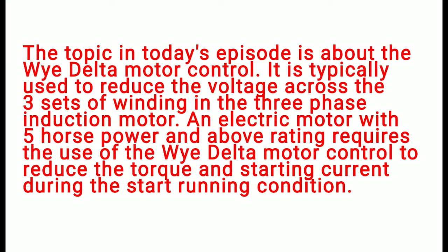The topic in today's episode is about the Wye-Delta Motor Control. It is typically used to reduce the voltage across the three sets of winding in the three-phase induction motor. An electric motor with 5 horsepower and above rating requires the use of the Wye-Delta Motor Control to reduce the torque and starting current during the start running condition.